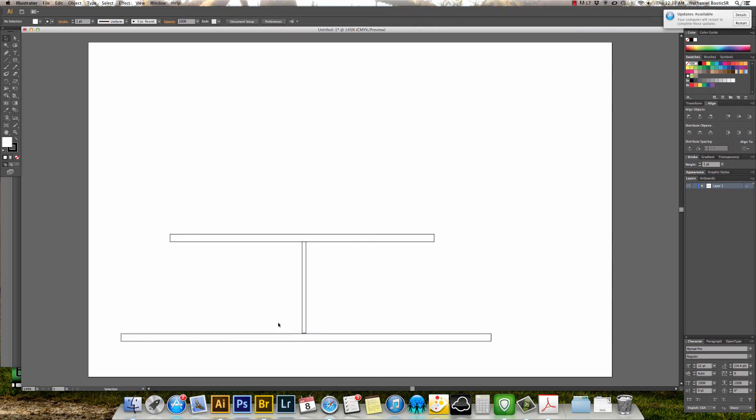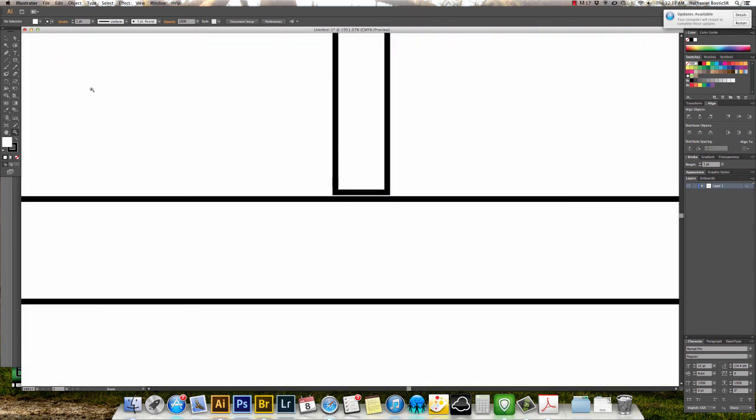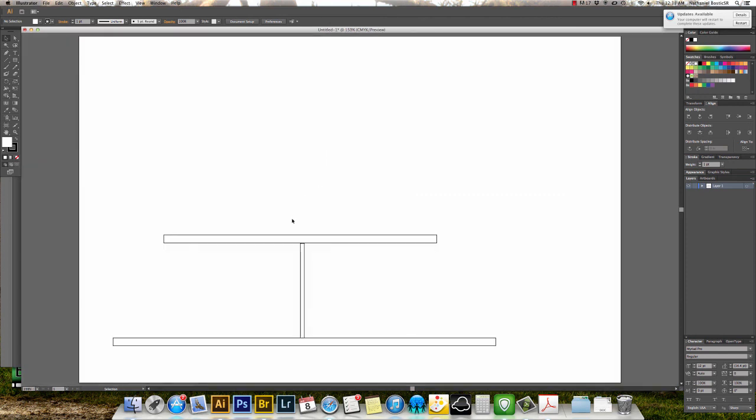If you don't get it lined up exactly, all you have to do is zoom in. I hit my Z key, which goes to my zoom tool, and I can just drag a box over the area I want to see. Then I can press V and line these up. What I typically do is use a smaller stroke. Zero to zoom out, I'll grab it all, go to my stroke, and I might use like a 0.5 because it's thinner and gives me more accuracy.